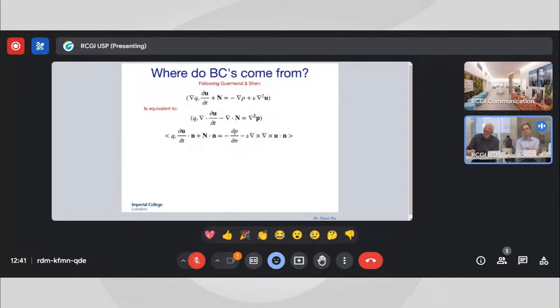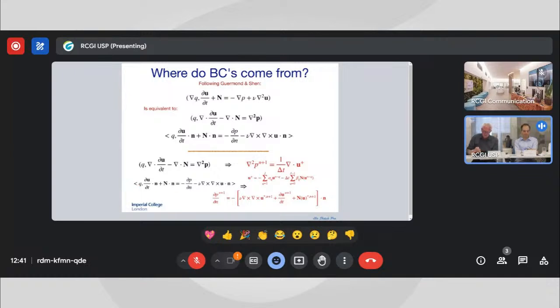So if I want to think of the pressure Poisson system in a strong form, which I generally like to think of mathematically, here's my pressure Poisson problem. I need an equivalent set of conditions, these angled bracket bits, that give me this pressure boundary condition that I'm imposing to get back to this weak form. So here's the Navier-Stokes equation, just multiplied by a gradient of a scalar. Done nothing mathematically too unusual. You think, why am I multiplying? But it's still the same equations.